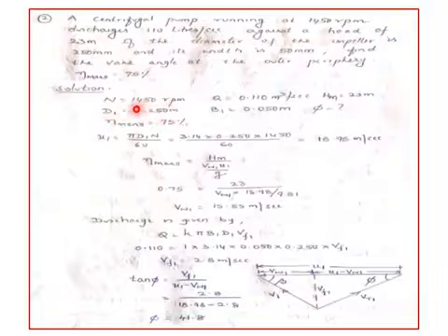So here it is 0.25 and its corresponding width is 50, that is 50 millimeters, which is 0.050 meters. So you have to find the vane angle at the outlet when the manometric efficiency is given. Since d1 is given, n is given, the first thing you find is the tangential velocity u1. So u1 can be determined, knowing d1 and n, which gives 18.98 meter per second.